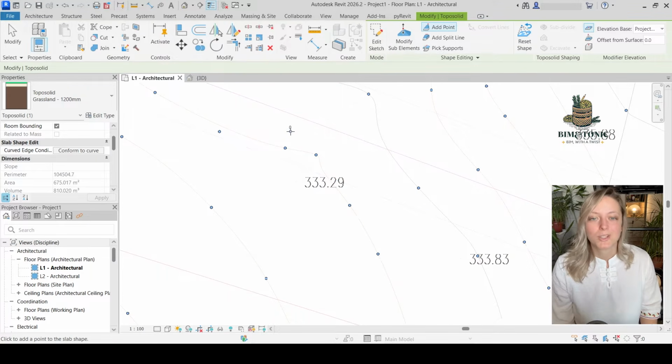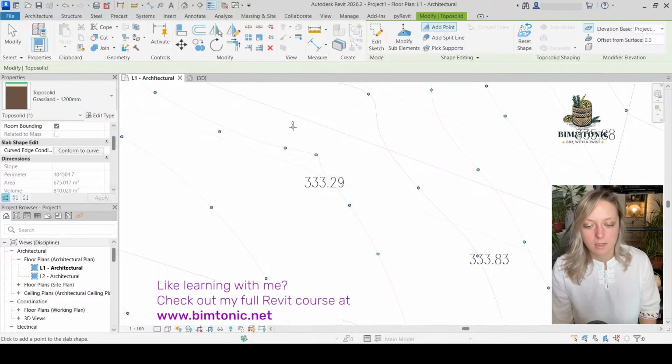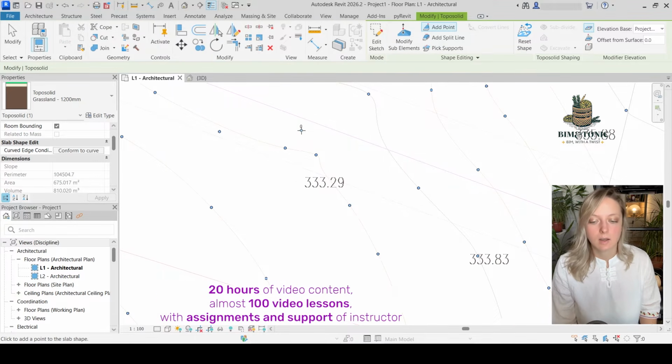So you have two options. You can either convert your entire file to meters and then insert these units, and then once you are done you can convert it back. It is not like in AutoCAD that it will cause you any trouble. Changing the units in Revit is harmless. Or you can simply insert these numbers in millimeters.